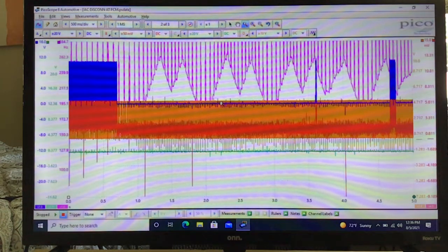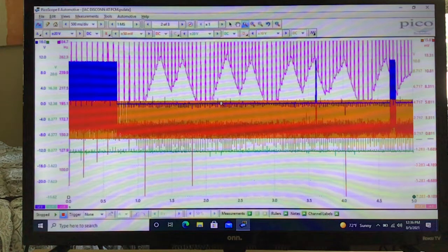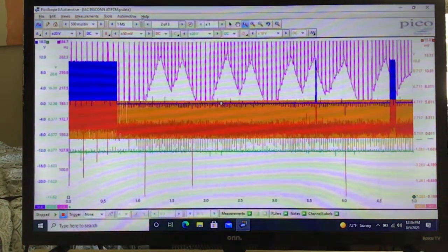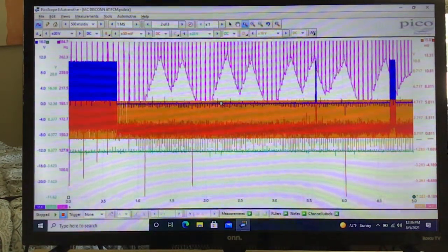I know they wouldn't use the cruise control cable. That has some electronic capability, but I would take it to the bank that they are not. That has got to be timing adjustments, the PCM saying I can't control the engine speed through the IAC anymore, so it's probably doing something to the timing. As you can see, that magenta math trace is just swinging up and down. See those, they look like teepees on a reservation, one after the other. I can't think of anything else that could affect that RPM other than timing. So that's an interesting capture.